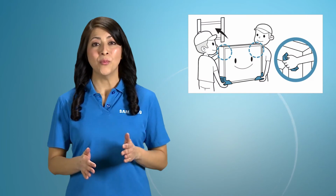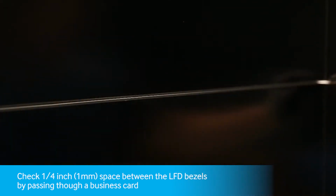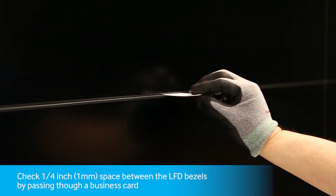Always have 2 people mount the product on a wall. Do not install your wall mount kit while your product is turned on. It may result in personal injury due to electric shock. Check to make sure there is 1 millimeter of space between the LFD bezels by using a business card to pass through. Let's start by attaching the set adapter to the LFD.